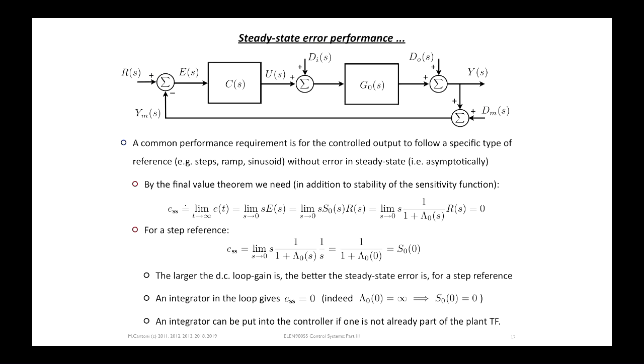But often we deal with cases where this is a constant, and it's uncertain in the sense that you just don't know what the size of the constant is, but you know it's some constant. So you model this as a step, and you're interested in the step response, and in particular the steady state response, because that's the same as saying, how sensitive is this to a constant here? Same for the reference.